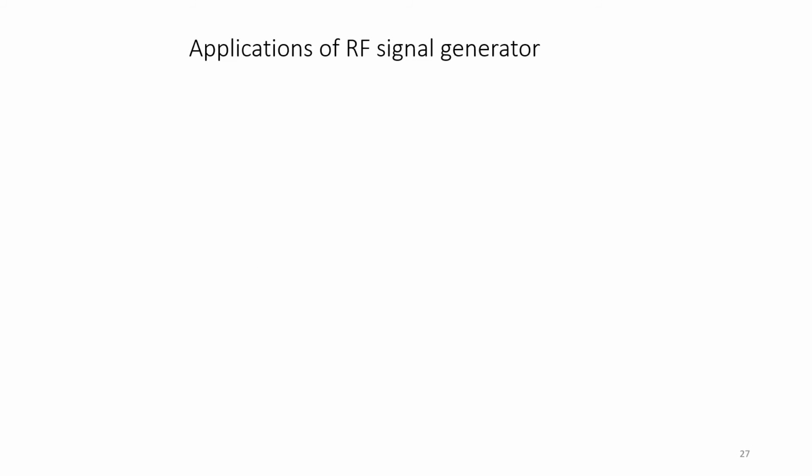You can also design RF signal generators with different frequency ranges varying from 50 kilohertz to 80 megahertz. The amplitude modulation, as I told you, may be 30%. For the output impedance, you can use either 20 ohms or 40 ohms. The output voltage is 50 millivolts.